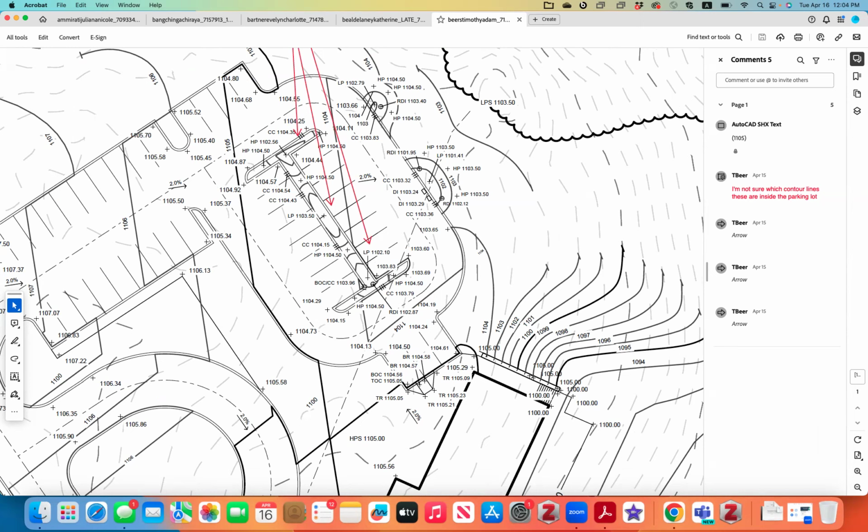Okay, it's a little more complicated on this one because you have a swale going through. So you kind of have to cut it open over here. And that's where your curb cut should be. And there's another curb cut over here, right? This is the lower one. So the calculation inside needs to be based on that one. Does that make sense?